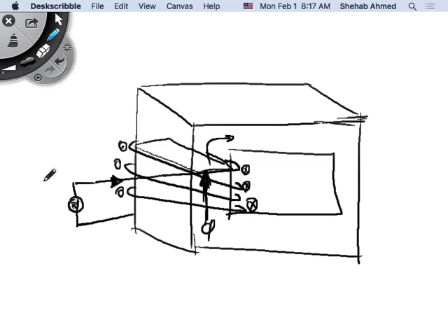So you have time-varying flux, and you have put a conductor in a time-varying flux. What will happen? Current will flow, and then force will result based on that, right? And this force is basically what you hear. The transformer, when you drive by, has this hissing noise, and it's because the laminations are pushing against each other actually. The flux is changing its polarity, and the force is changing its polarity, and the laminations keep hissing because of the magnetostriction force that is resulting based on this.